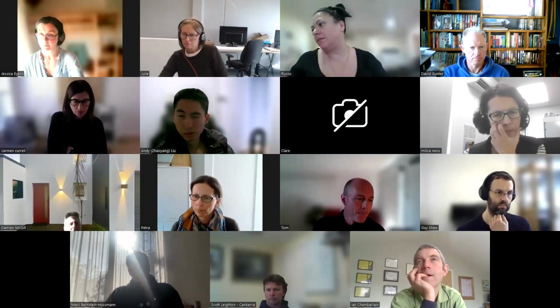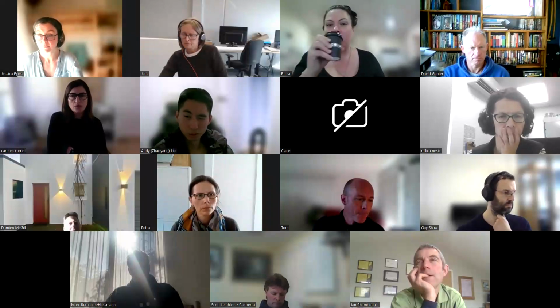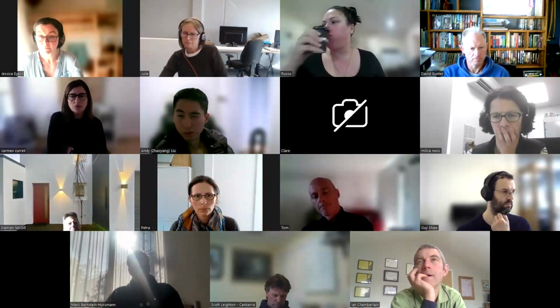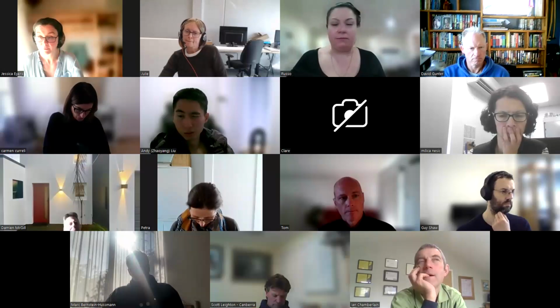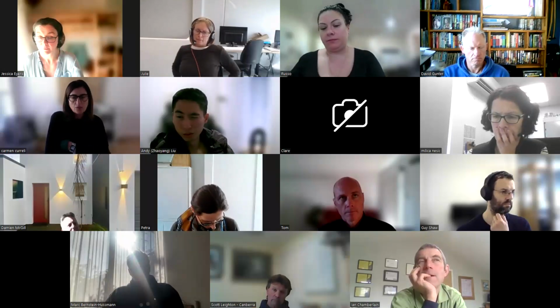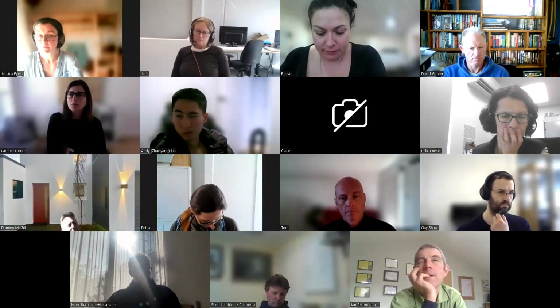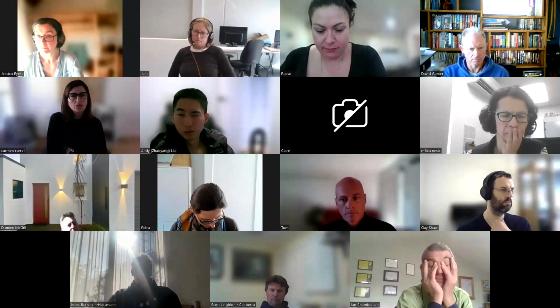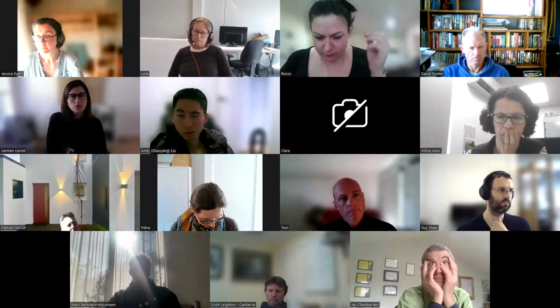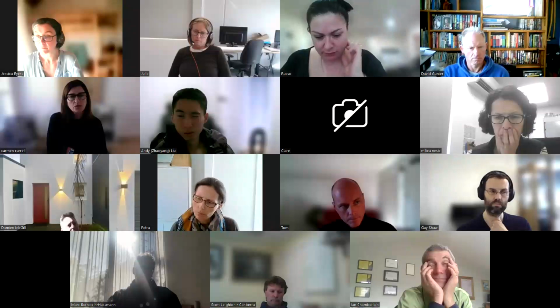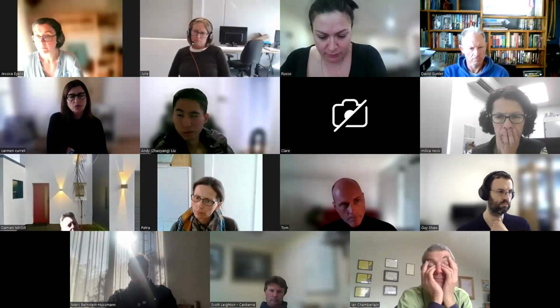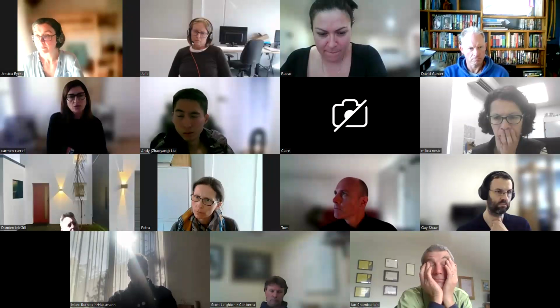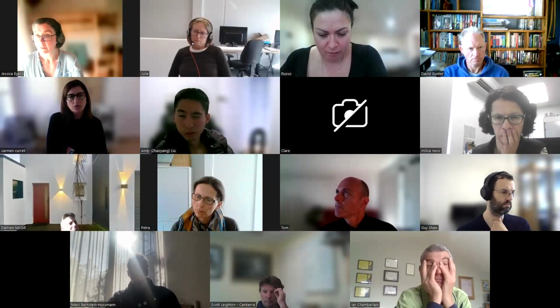I was just going to pick up on that ground sheet question, Jessica. If you put a concrete slab in the U value and you put it against ground, obviously it can make an assumption about what's going on. If you're doing a suspended timber floor, do you just put the U value against ambient air so that it doesn't assume it's on the ground, or still put it against the ground because it makes some adjustment for the crawl space, a protected crawl space or something?